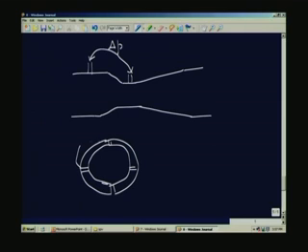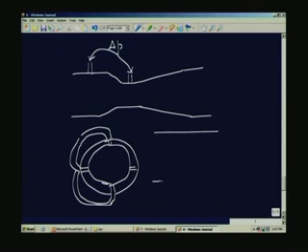That means that the pressures are all communicated to the same port, and that means that I am going to measure the average of the pressure in the 4 taps, in this case 4 or more than 4. So, if you look at the cross section of the pipe, the pressure taps will be there like that, on the wall here, on the periphery, all of them connected to the same port or the same hole, which is going to be connected to one arm of the pressure difference measuring device.